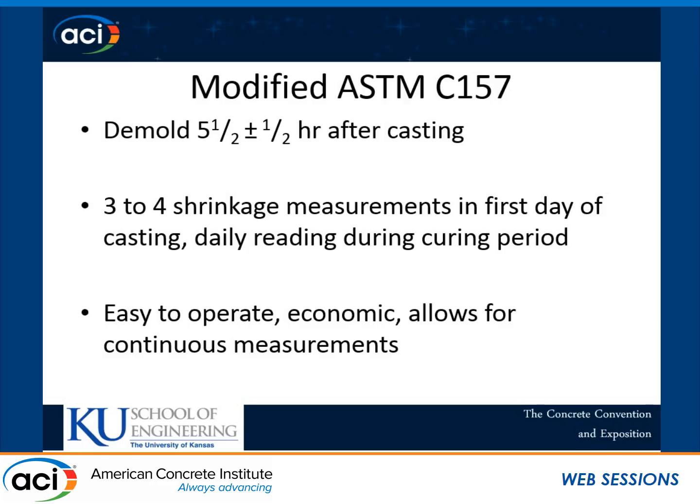Now, since we demold the specimen early, we can take 3 to 4 readings during the first day, and we also decided to take length measurements daily during the curing period. Since this test method is based on ASTM C157, it's very easy to operate and very economical. If you're running C157 already in your lab, you don't need to add any additional equipment. And finally, this test method allows us to continuously monitor the deformation during the curing period and drying period.